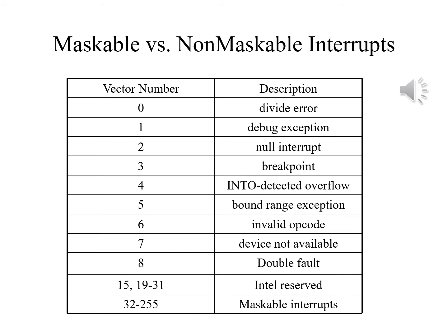Most processors have two interrupt lines. One for unmaskable interrupts for events too important to miss, such as memory exceptions, division by zero, and invalid opcodes. The other one is for maskable interrupts, which we will mask to avoid interrupting critical sections.